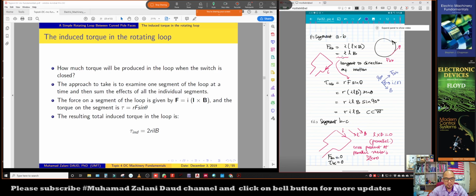As you can see, using this equation F = ILB, we can find the torque induced at the AB segment. Using r F sine theta, since we know that theta is 90 degrees, because at segment AB every component is perpendicular to each other, finally we get rILB. So the torque at the AB segment is defined as rILB, which is in the counterclockwise direction.